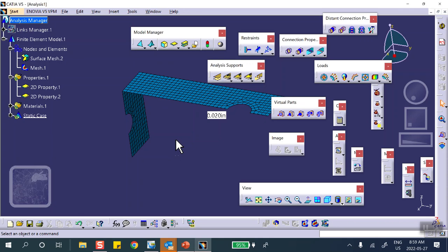I can draw a horizontal line, extrude it, vertical line, extrude it, and there's going to be a seam there. You make the hole on top of this, you make the hole on the side of this, the usual way that we did, and then you create a connection between them and make it fasten. Or join them. You can also join them. In other words, when you drew this guy and extruded this guy and extruded and then you made the hole, fine, join them. Then you don't have that problem. Any questions?